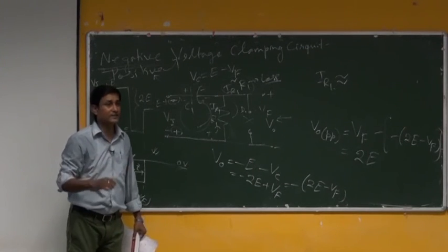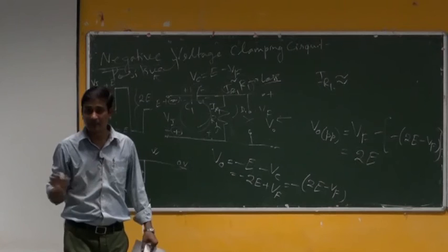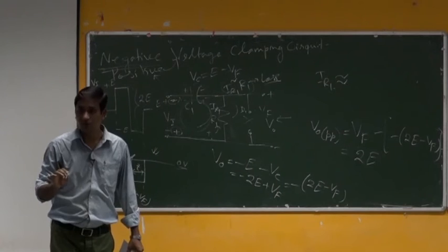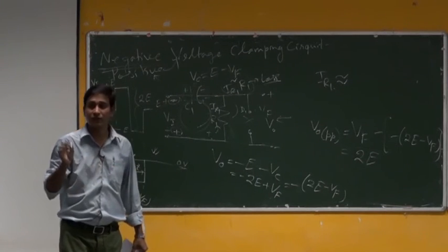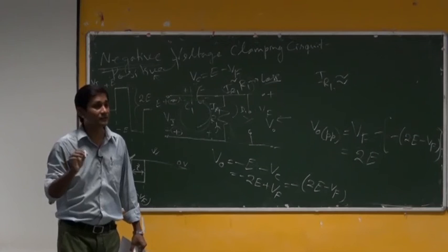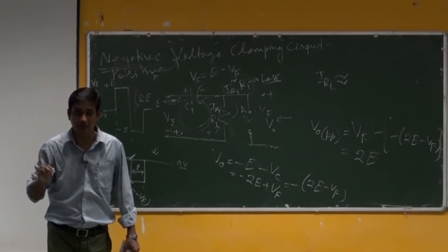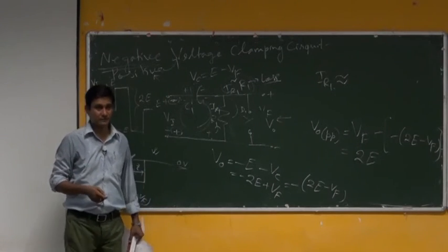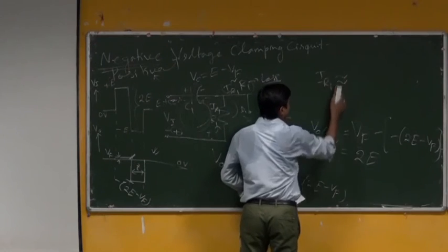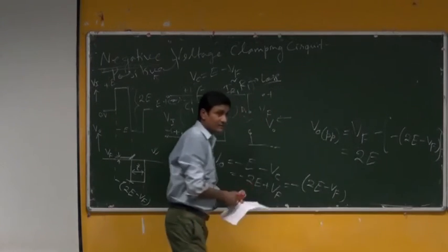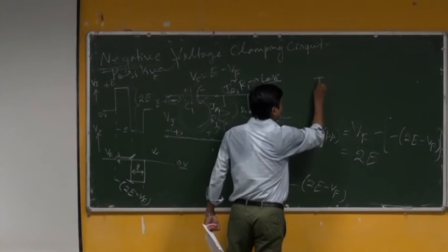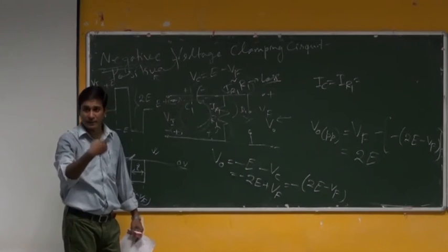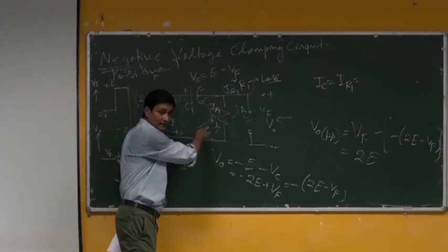Since in the capacitor the voltage cannot change immediately, but current can, we should not analyze the circuit where the capacitor is involved in terms of voltage, but in terms of the difference of voltage with respect to time, or in terms of current through it, using the continuity equation of a capacitor. I hope you have heard the term continuity equation of a capacitor, through which we will find the current IC through the capacitor, which is the same as IR in this place.